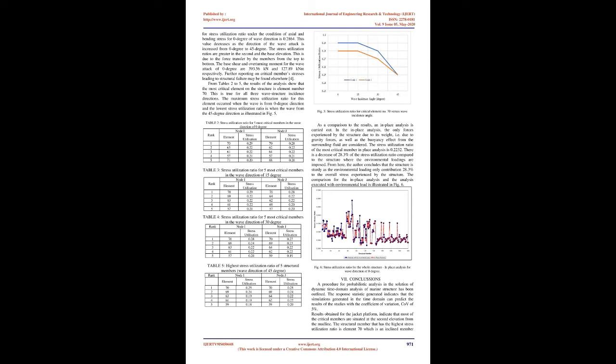6. Results and discussion. The simulations are carried out in 4 wave incidence directions: 0 degree, 15 degree, 30 degree, and 45 degree. Due to the symmetrical features of the structure, the simulations are only performed up to 45 degree. The output generated from the simulations is axial stress for node I and J, bending stress for node I and J, and nodal displacement. These stresses are due to external and transferred forces exerted onto the structure.